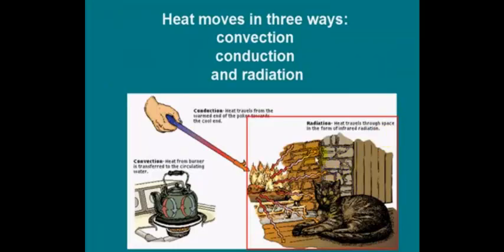All right, that's radiation. If you've walked through a warehouse with radiant heaters, it's 40 or 50 degrees in the warehouse, but walk up to a box or a table and put your hand on it, if they're using radiant heat, that object is warm. And that's how radiant heat works. It heats up the object just like the sun heats up the earth, and then that heat radiates back out to space again, which is cold, because hot always goes to cold, and on the way out it warms up the air. The same with radiant heat in a warehouse. Heat up the objects, they radiate heat to the air and temper the air.